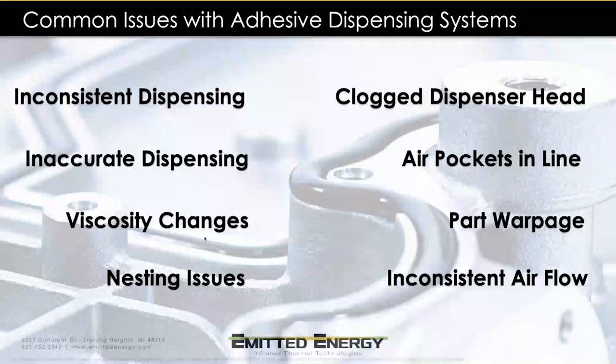Clogged dispenser heads, of course, you get in there, the dispenser head has maybe some viscosity issues, maybe start and stop of the machines. But what ends up happening is that you have dried or a cooled material in the head, and we're not getting consistent throughput.